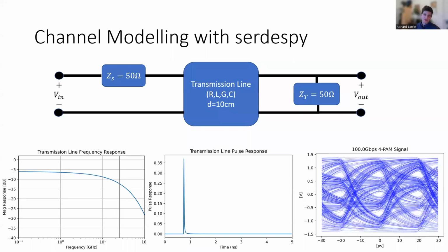Hi, in this video, we're going to build a model of a transmission line and run some simulations to see its behavior using SerDesPy, a free Python package for SerDes simulations. I'll be explaining how to do this, but skipping over a few of the details that I went over in the first video, where I explained how to install SerDesPy and some of its basic functionality. So I suggest you check that video out first.